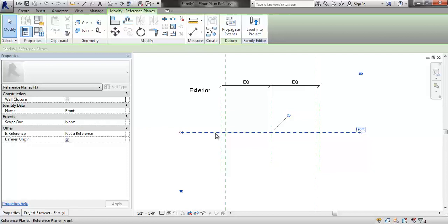So within plan, right now in plan we have these two reference planes. Mullion. I'll need to build in a line for one, my slab edge cover, and then I'll build off each one of those. So I'll be handling offsets within this, to move it inside of that slab or outside of that slab. Makes sense? That same idea of offsetting is going to be for case A too. So we'll try and do both. Any questions on that?